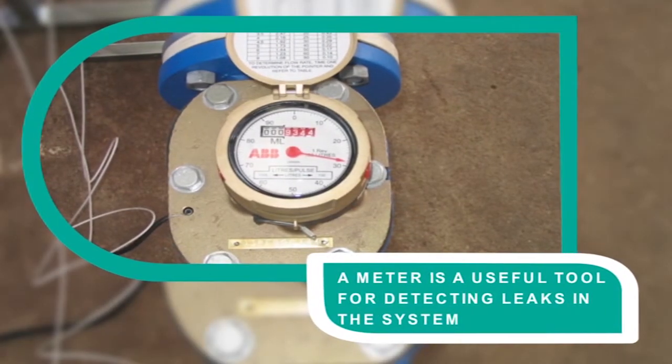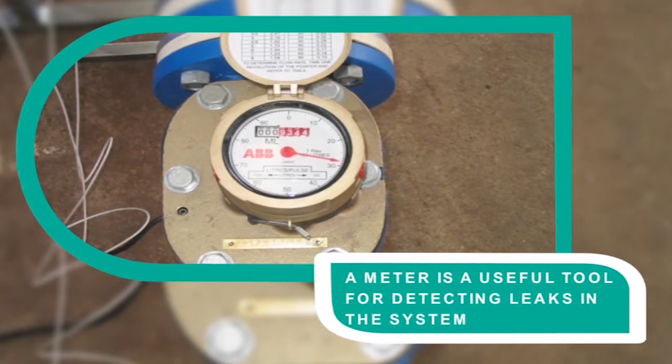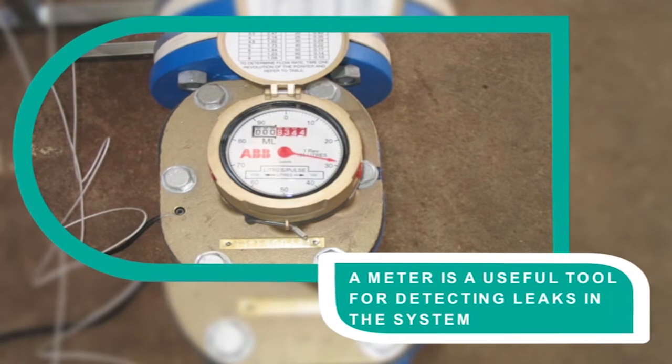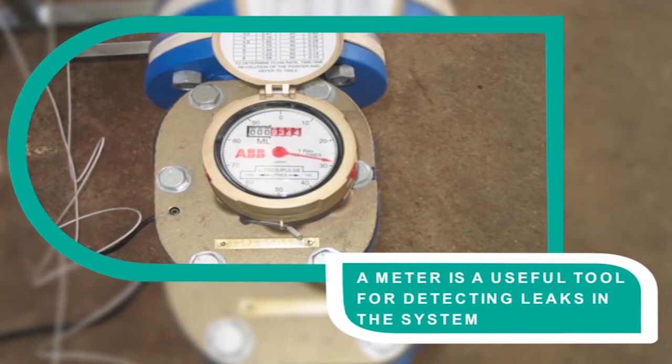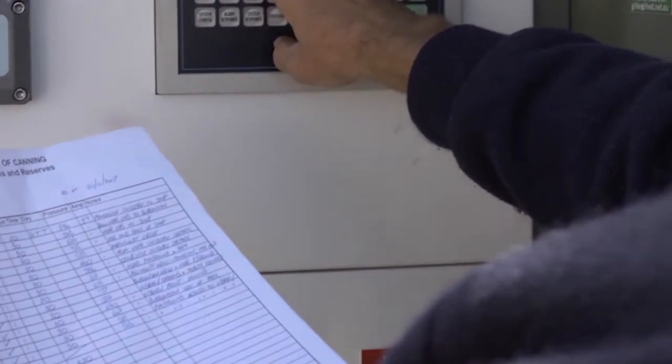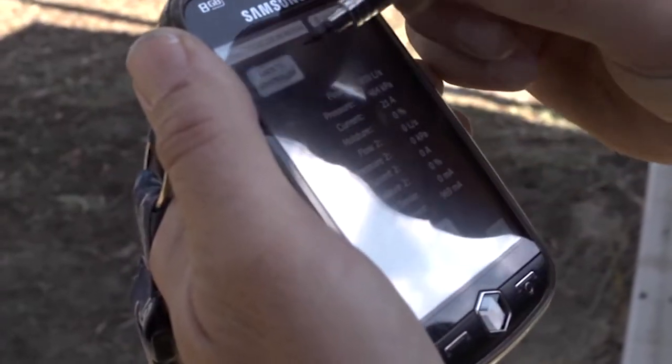For example, flow rates and water use go up if a sprinkler head has been broken off or damaged, causing a leak, and flow rates will go down if sprinkler heads are blocked or if a control valve is not opening fully. Meter readings can be taken manually or by remote, using logging devices connected to a central location using telemetry or GSM technology, or these days over the internet.